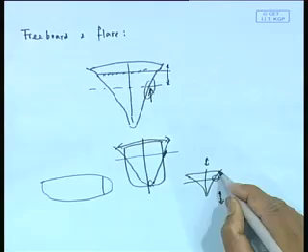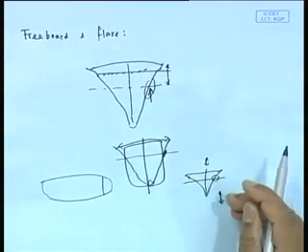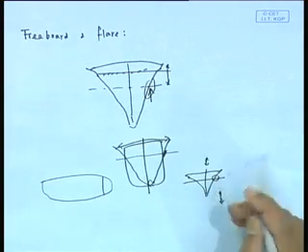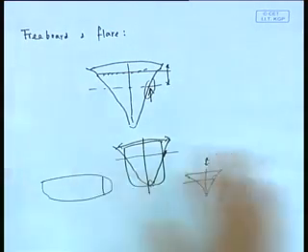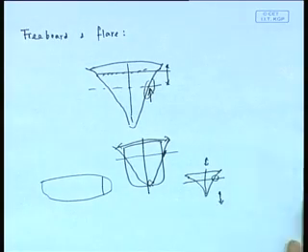In other words, if I were to tell that look, flare is necessarily increasing slamming, that is not true, because that depends on the motion itself. Now if you have a low flare, then the motion may be somewhat low. So therefore all these criteria are, as I said, there is no hard and fast rule. What it comes down to is that the most important factor is basically length. Beam is not so important, but draft is important, because if you have a very shallow draft, you have bad motion. Forward sections become somewhat important from the deck wetness and slamming point of view.